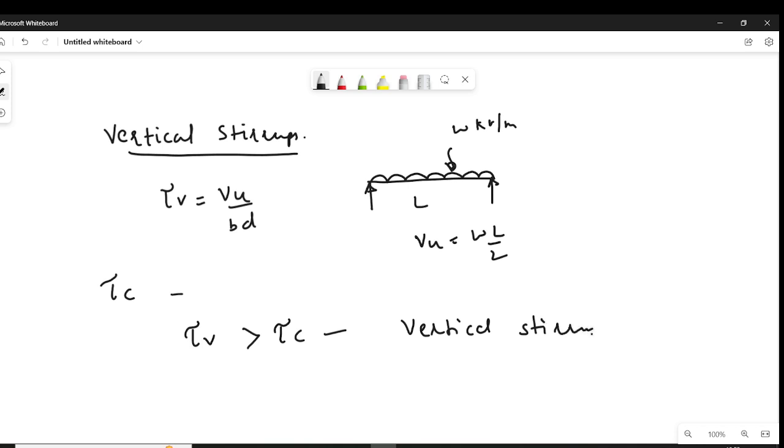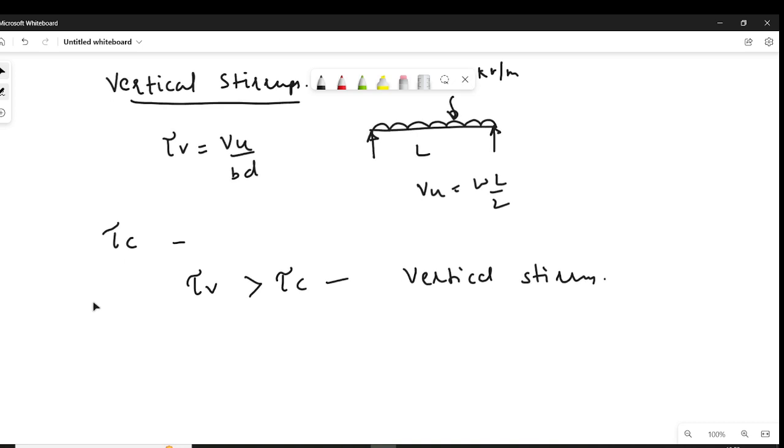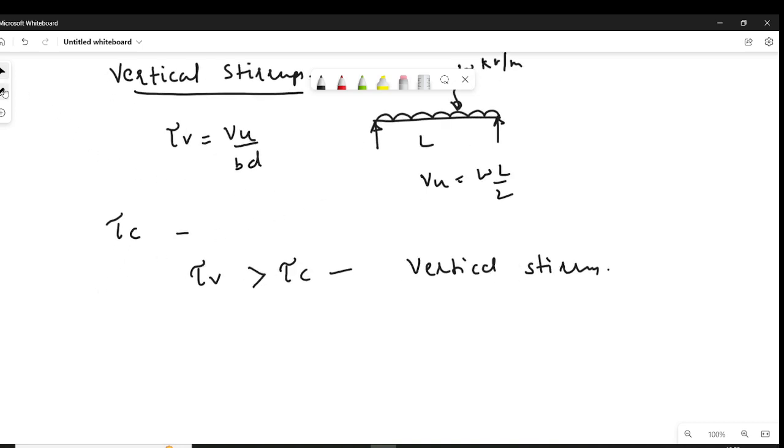First we have to find the net shear force in the beam. What is that? I will tell you. Vus is the net shear force. Vu is the shear force coming on the beam, and some of the shear force is resisted by the concrete.